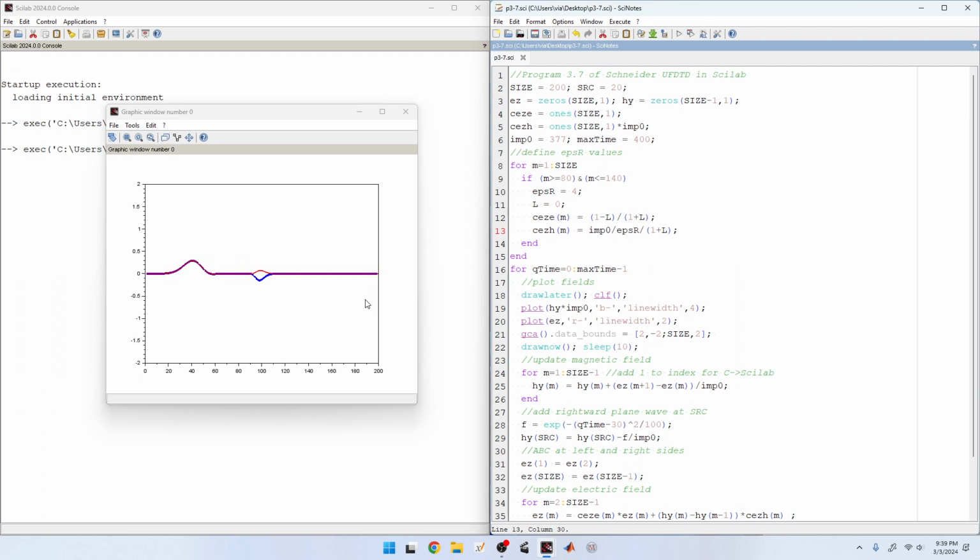And there we go. But now we can put in some conductivity effects. Let's make this loss term 0.01. Let's see what that does. Here comes our field, goes into the medium. Now notice that amplitude starts to drop off. That's lossiness. Now the reflected one, so everything is decaying exponentially inside that medium. If we make this loss term 10 times as big, here we go into that medium, and wow, that just really decays extremely rapidly.